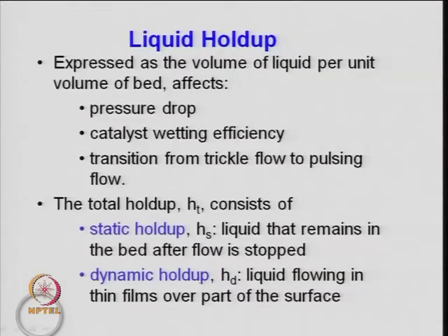Liquid hold up is expressed as the volume of liquid per unit volume of the bed, a very important parameter when we look at the hydrodynamic study, which can also be done by computational fluid dynamics by selecting a proper volume of the system.